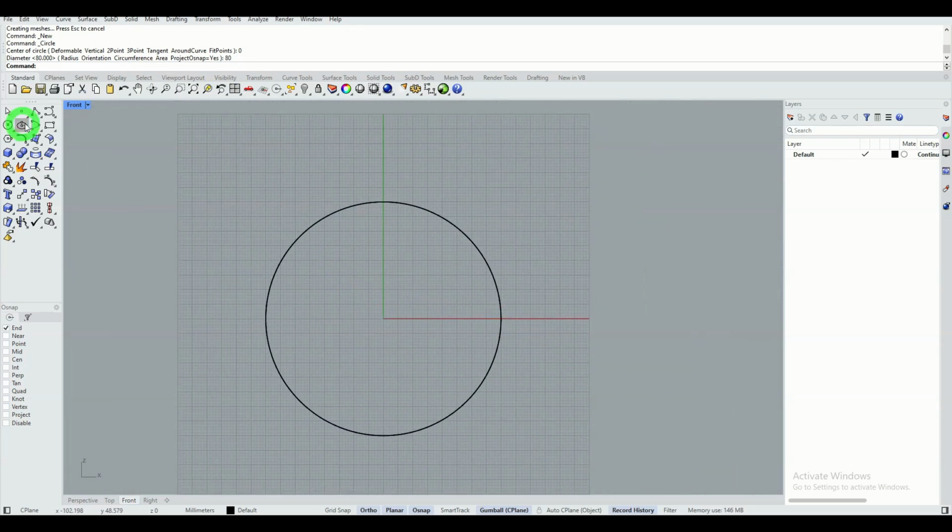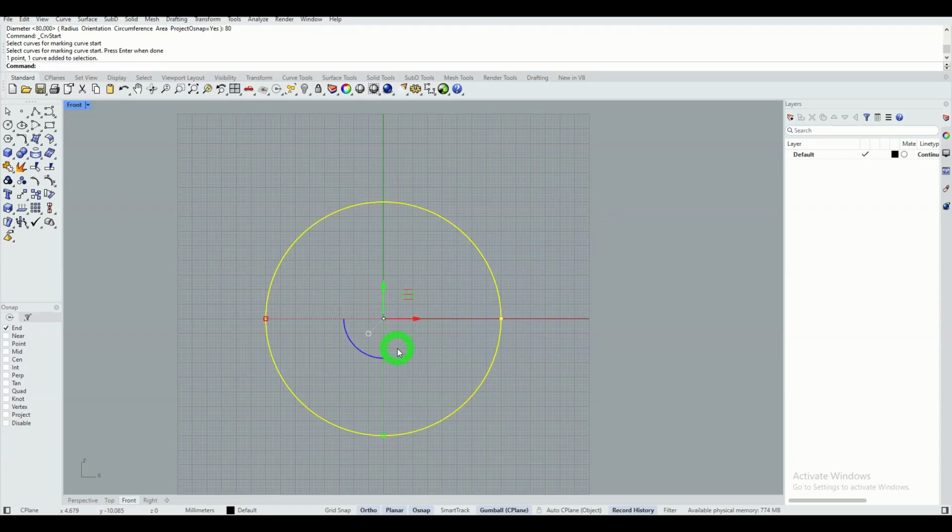Then highlight the starting point of this curve. It's a circle, so the starting point and the end point coincide. I select that point and the circle and rotate them by -90 degrees to move the starting point and the end point vertically.